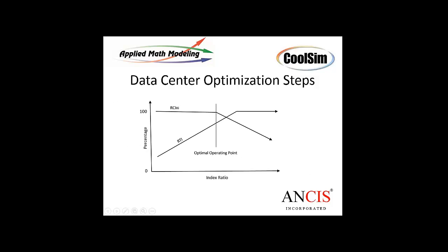Now, this is a little chart that I made to show sort of the effect I was talking about. RTI often starts off low because we're supplying too much air to the data center. RCI high is not a problem because we've got too much air in the data center, and oftentimes this is because the data center isn't full and it was built to handle certain capacity and you're only at a fraction of that capacity right now. So you're in a situation shown over here on the left. RTI is low, RCI is high.